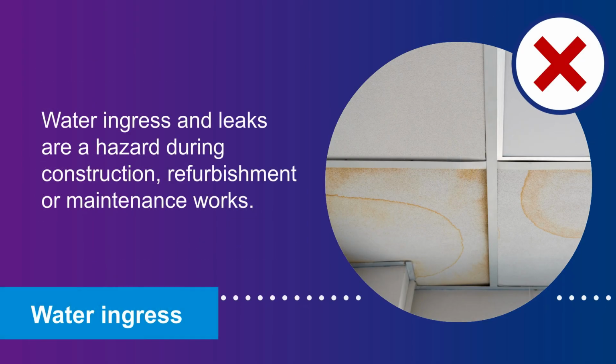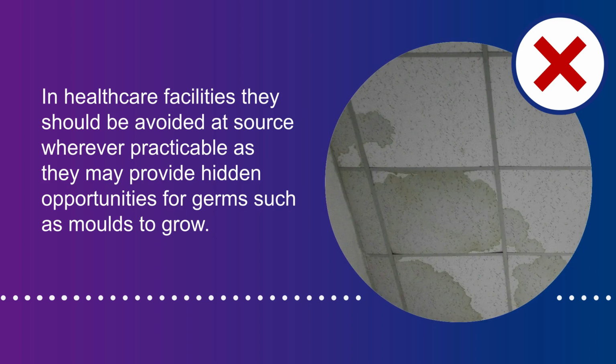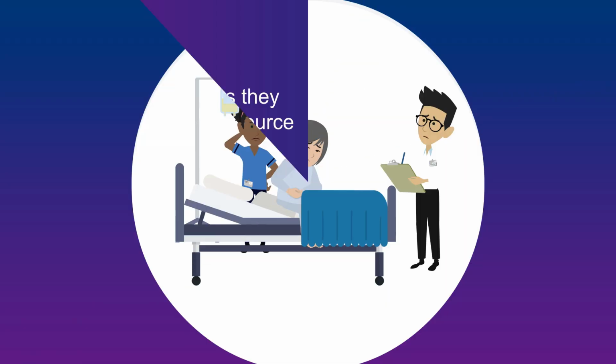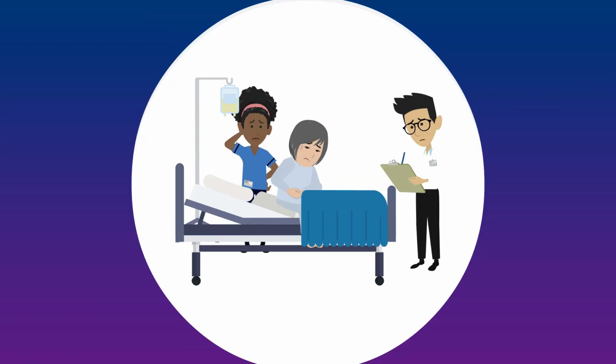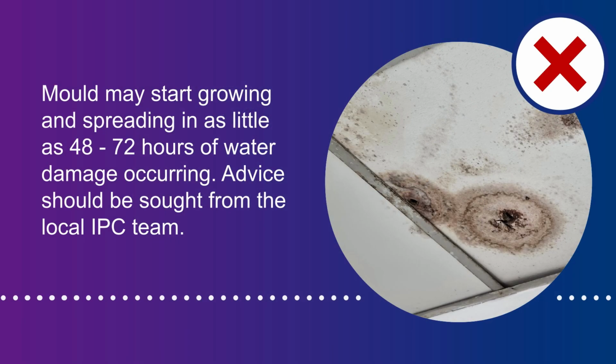Water ingress and leaks are a hazard during construction, refurbishment, or maintenance works. Where it may be typical for these to occur on non-healthcare sites, in healthcare facilities they should be avoided at source wherever practicable, as they may provide hidden opportunities for germs such as moulds to grow. Sometimes issues such as this aren't recognised until it's too late and patients have become seriously unwell as a result. Mould may start growing and spreading in as little as 48 to 72 hours of water damage occurring.